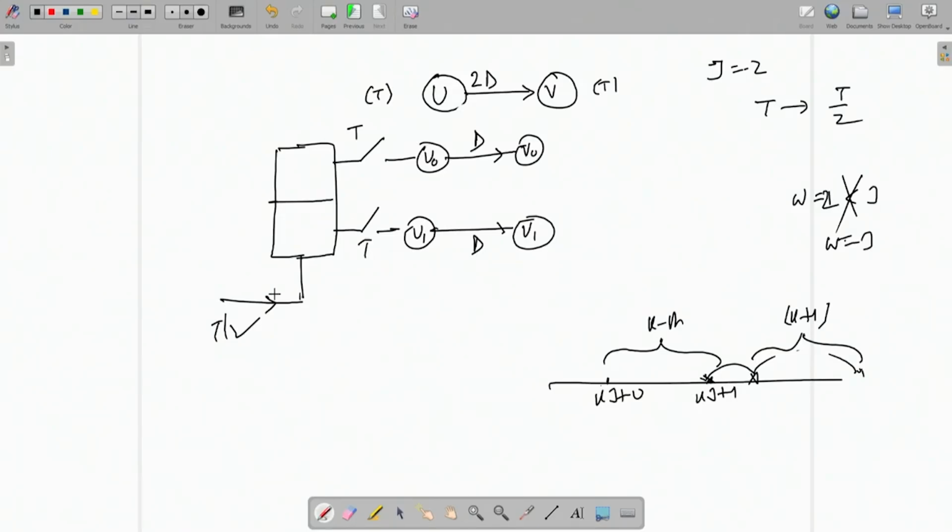So while trying to achieve higher speed, I end up in a problem where the critical path increases. So I cannot really increase the system clock, and therefore I cannot get that advantage at the input clock. Because unfolding always leads to a reduction in the number of delays in the unfolded edges.